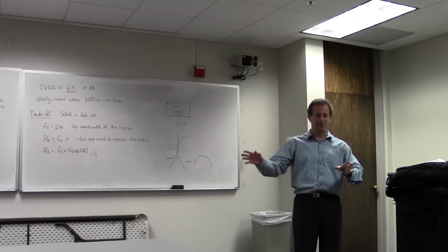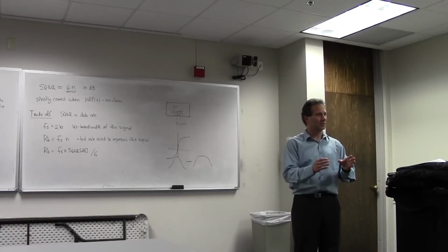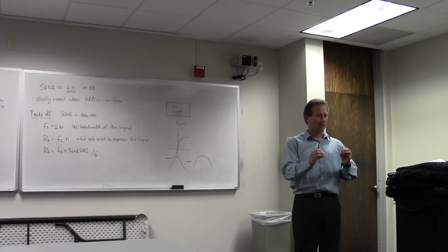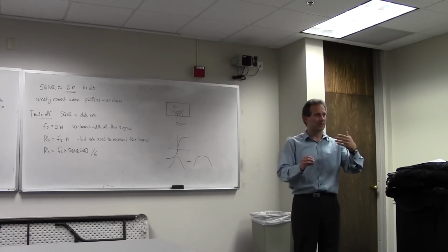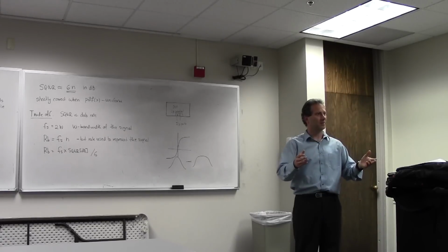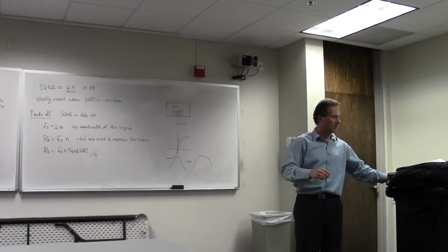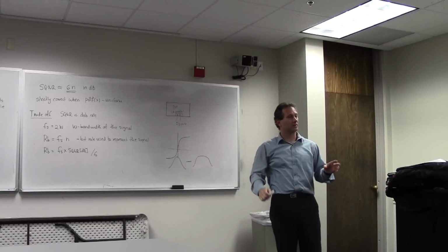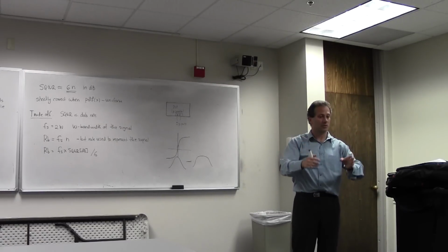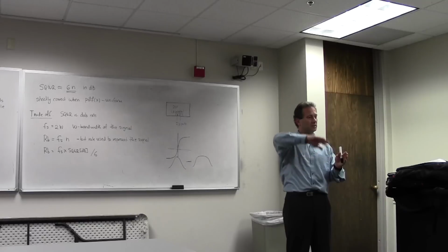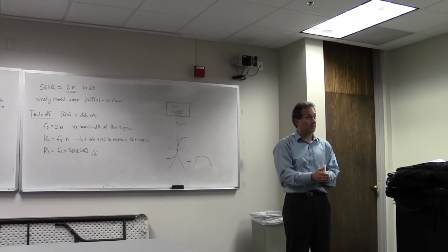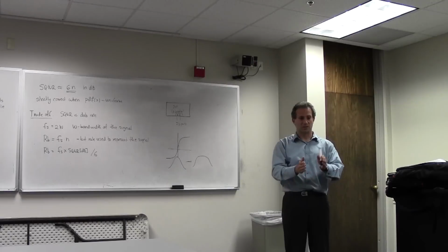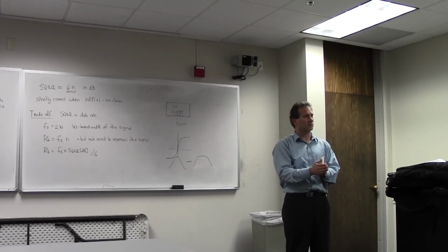Right. No, in our terms here, it takes the PDF of the signal, where most of our signals are dwelling quite a bit of time around 0. You all have capabilities of that. Say something, record your voice, and then display it in MATLAB, and you will see that the signal is a lot of times around 0. It is kind of doing this, and then there are your vowels. Plot your histogram, and you will see that it has a really peaked spectrum at 0, right? So that means it has the highest probability of being in a range of the quantizer where the SQNR is the lowest.